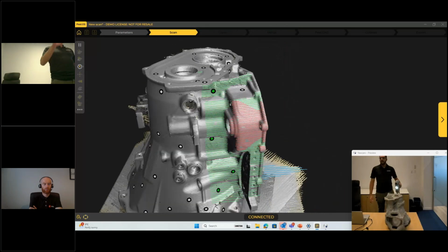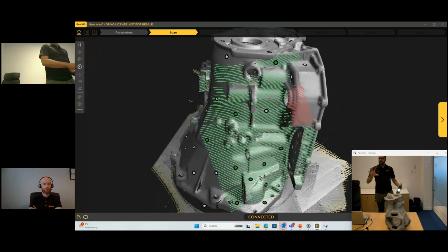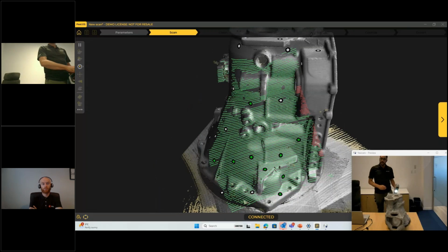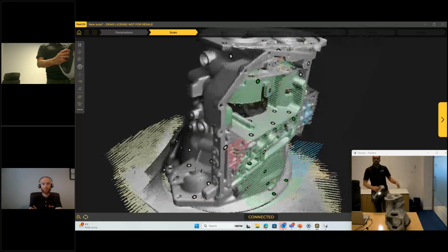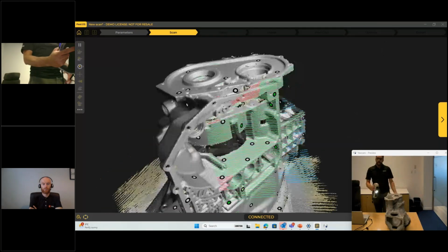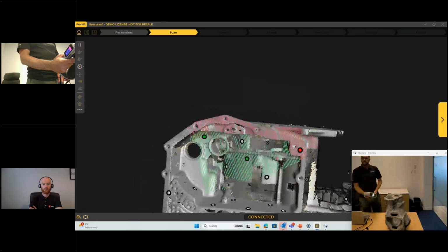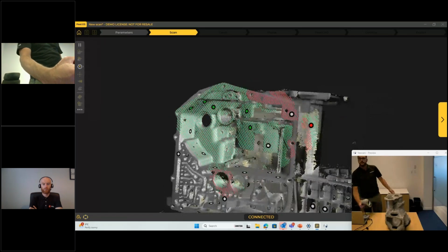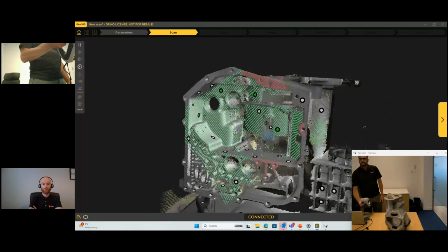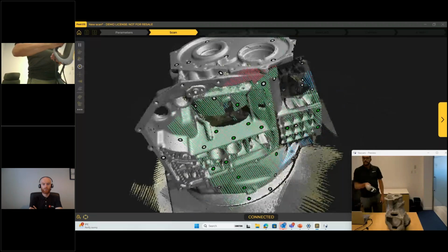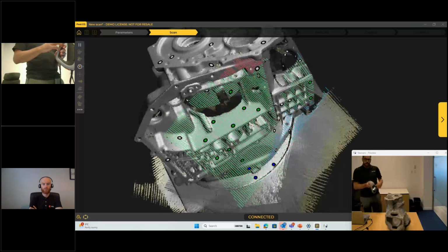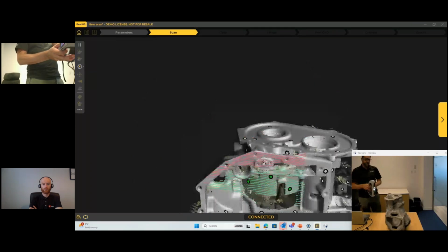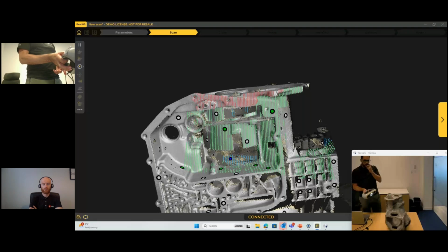The scanner is reading those positioning targets, and the cameras are reading the positioning targets and reading at the same time the deformation of those lines, creating the 3D model. At different angles, we can hold the scanner in a vertical position, or we can scan holding it in a horizontal position as well.